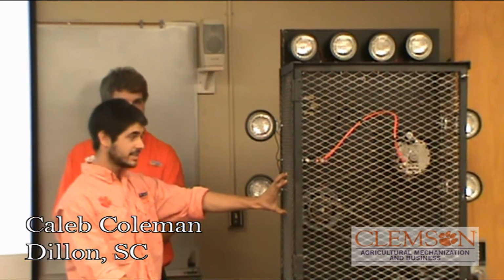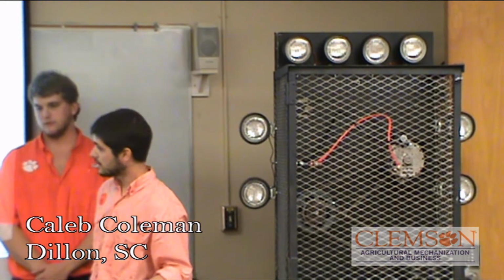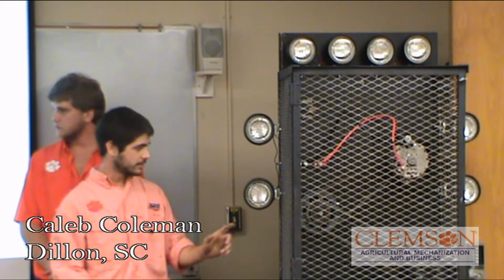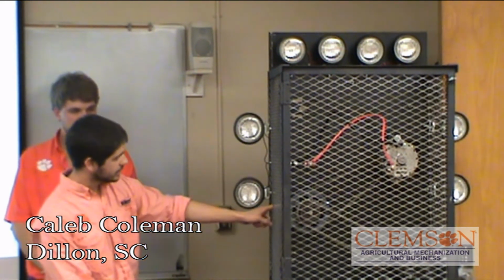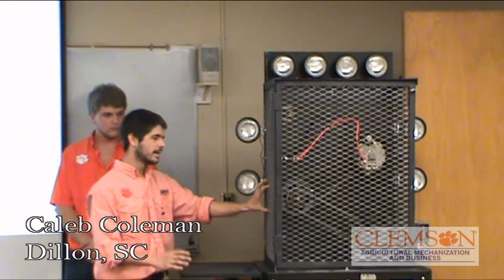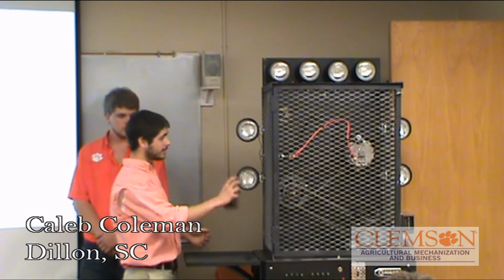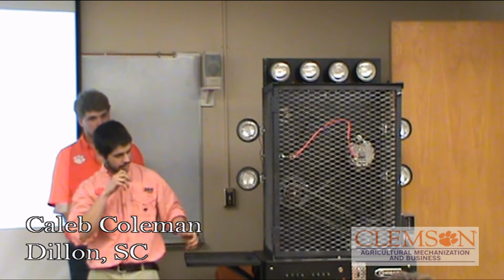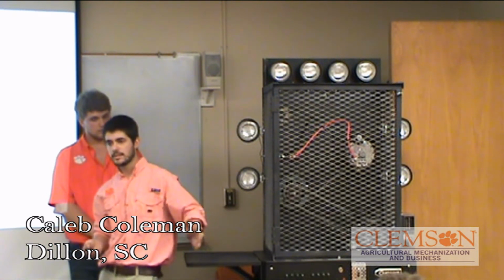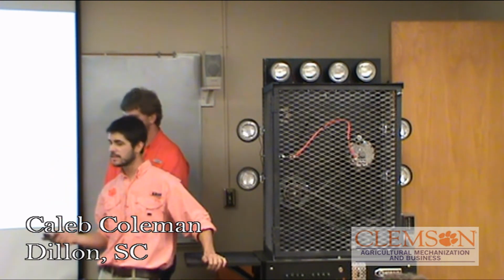That's another place efficiency is lost. And then your alternator, efficiency is lost there. So to get around that, what we did is we did a direct drive from our motor, and for our first stage we did just the alternator in this area right here, and that way we got all 3 losses in the same one. And then from that we did 1 belt drive to our alternator, so we did one extra step. And in theory, the only extra loss of efficiency should be that extra belt drive. So from that, you can calculate just the belt drive loss.